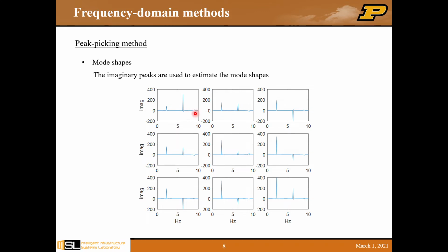So again, we obtain the matrix of the plot here, and then to obtain the first, second, and third modes, we easily just obtain that by connecting the first peaks in the different figures in the first row of the FRF plot. Okay, so this is actually the first mode. You can also obtain that in the second row, the third row as well, for the first mode.